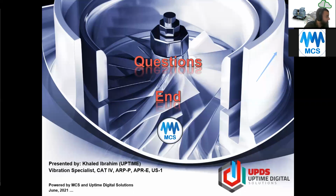Maybe Salah is. Do we have pros and cons of online monitoring systems currently? See, the pros and cons I will tell you. You can control it by knowing the failure, the most catchable or sensible moment when you have a failure. This is where you can calculate something we call the consequences of the failure. So if you have a steam turbine, for instance, it just stopped and you don't know what the reason is. When you open it, you find that you have a rub, like what Mr. Salah discussed, and this rub has damaged your bearing. And you have a very special bearing and you don't know how long the lead time or the expediting time will be until the new bearing is delivered. So your machine looks like what?